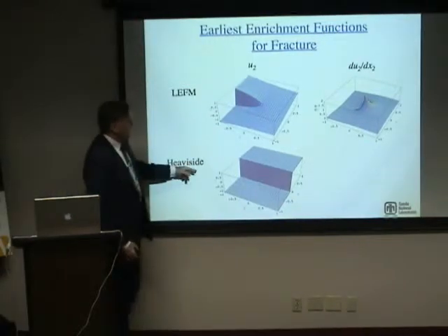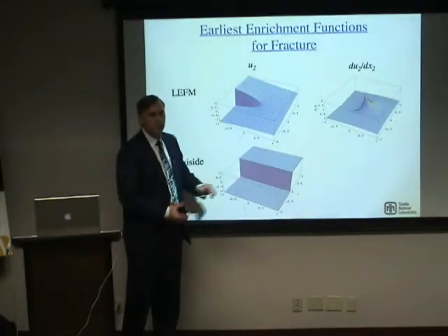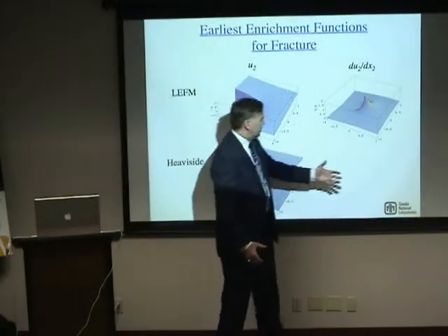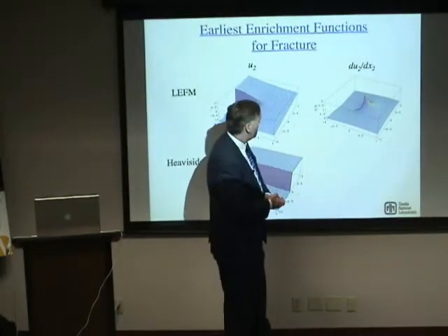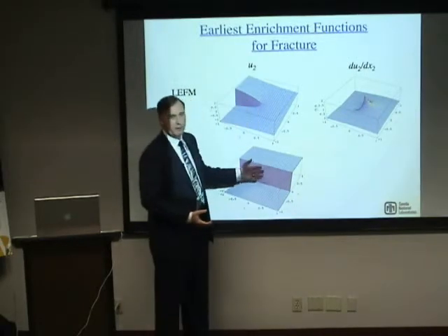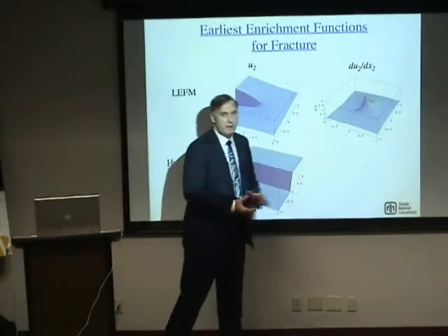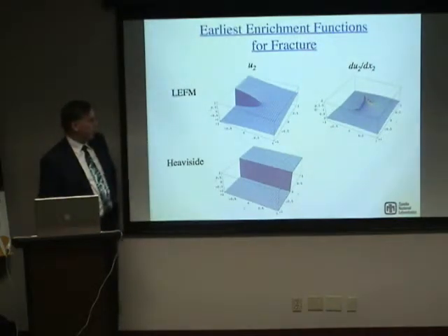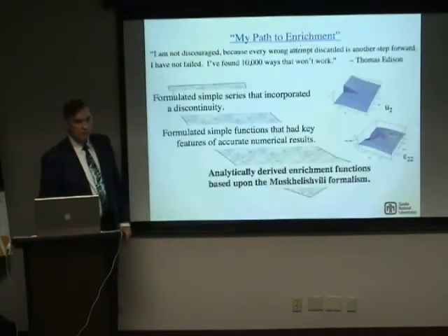Now, on the other hand, this was what also was first used for the cohesive crack problem, and you'll notice that it doesn't have a plot over here because the zero plot's sort of boring, but if we look at the gradient of this, we end up with nothing, right? So this enrichment function doesn't contribute to the gradient around the crack. Rather, you have to pick that up, as I mentioned earlier, through having sufficiently fine polynomials.